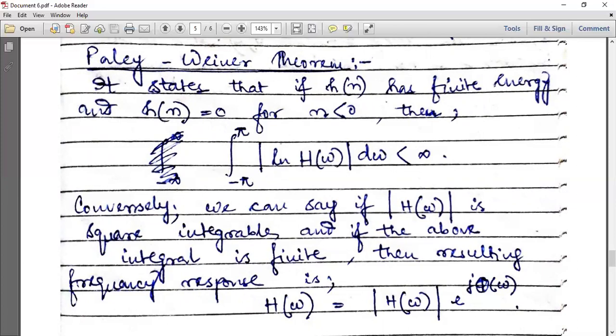The magnitude need not be constant in the entire pass band of the filter. A small amount of ripple in the pass band may be allowed. In ideal cases these ripples are not present, but in practical cases they should be allowed, otherwise you can't get proper answers. Also, it is not necessary that the magnitude response should be 0 in the stop band. In the ideal case it should be 0, since you are not allowing those frequencies. But in a practical application, there can be a very small magnitude response in the stop band. A small amount of ripple in the stop band may be allowed.